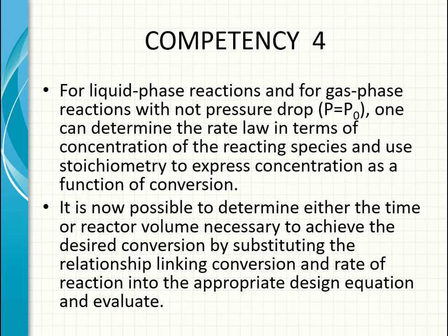For liquid phase reactions and for gas phase reactions with no pressure drop, that means the pressure is constant, one can determine the rate law in terms of concentration of the reactant species and use stoichiometry to express concentration as a function of conversion.